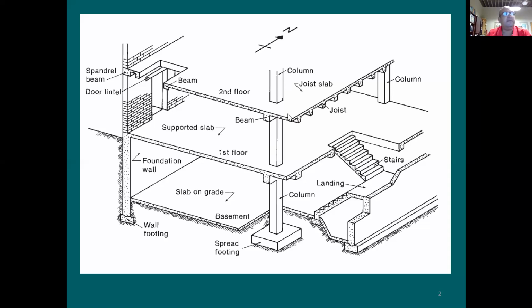You say from this level, it says this much pounds or kips. Same thing for this column, same thing for this wall. And then you keep track of them. And then you say, right at the foundation, I have the loads coming for column. Let's say this is gonna be C1 coming from here and all places. Make sense? All right.